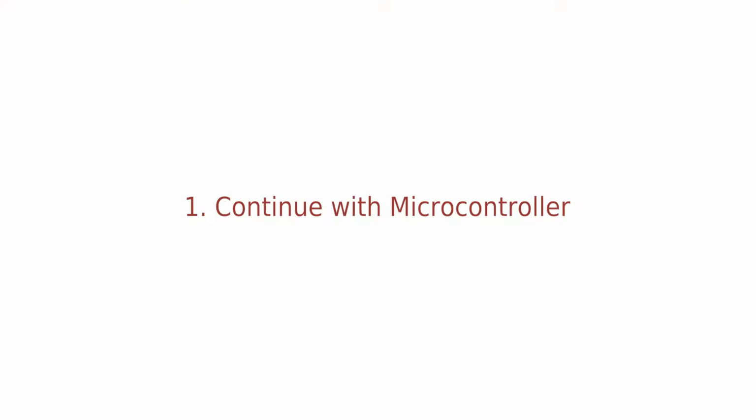Now back to the original topic, how to migrate a microcontroller-based design to an i.MX-based design with HMP. There are four basic options. The first and maybe obvious solution is to continue in the microcontroller world. If available, select a higher performing microcontroller and add new functions and features to your existing applications. Continue using an RTOS. Unfortunately, this is often not an option, since you likely have run out of memory and/or performance.